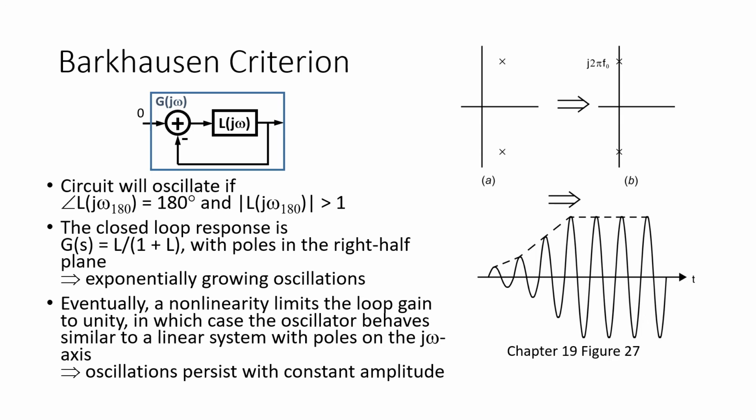Next, we want to understand the jitter and phase noise characteristics that typically arise in integrated circuit oscillators. To do so, we're going to make use of a linearized model for the analysis. Just a quick caveat here: linearized analysis is generally not going to be accurate for oscillator circuits, because oscillator circuits generate quite large waveforms. As a result, transistors operate non-linearly and small signal analysis is generally not applicable.